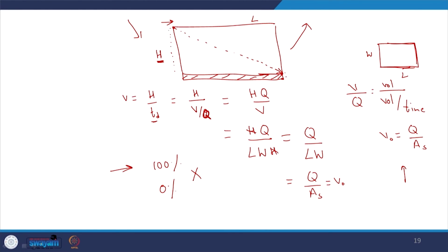So, if a particle comes out here with a settling velocity just equal to V naught, that will be removed, fine. But if it comes out here, let us say, with a lesser one, I guess I should have drawn a better figure, it has to be such that Vs is V naught by 2, or 2 Vs is V naught, and this particle is out here. So, this particle is traveling at a Vs such that it will just be removed at this point, but we see that it came in at h by 2.